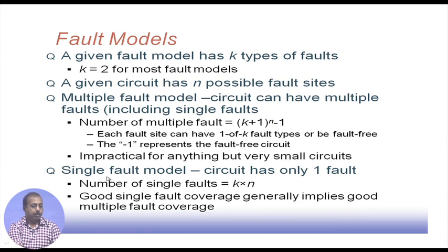This type of fault model, the single fault model, though very simplistic, helps in developing algorithms for doing this testing efficiently, and it has been observed that good single fault coverage generally implies good multiple fault coverage.